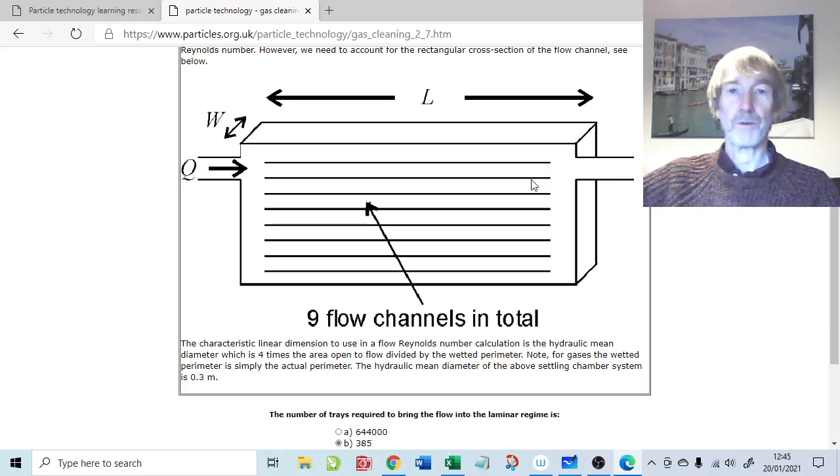So what is not lost is just that we have to adapt the model to fit the situation being driven by the fact that we've got 10 meters cubed per second flow rate, which is obviously quite a high flow rate, but fairly typical of gas effluents in industrial processes. So the next question is how to deal with the fact that we have the turbulent flow. It's the same system, but we will take into account the turbulent flow.